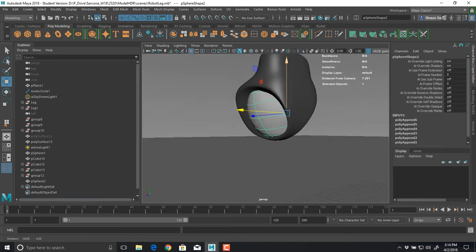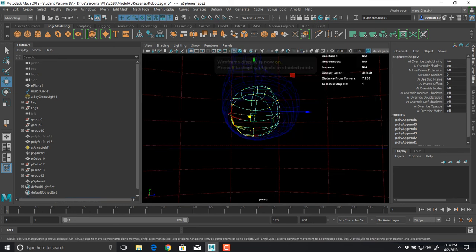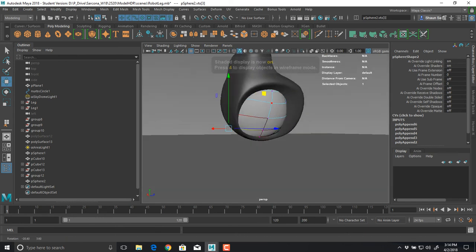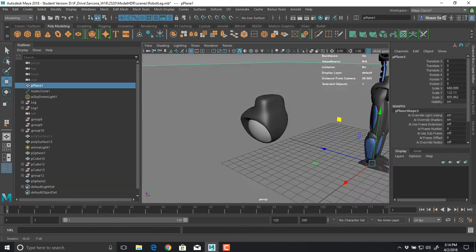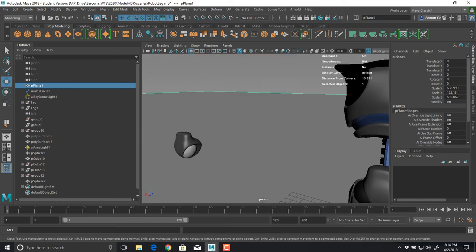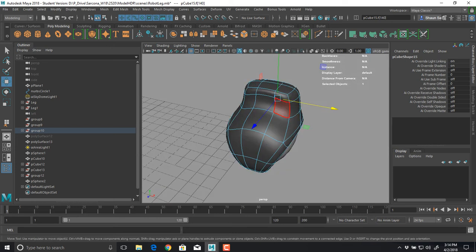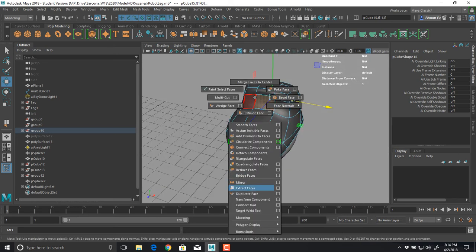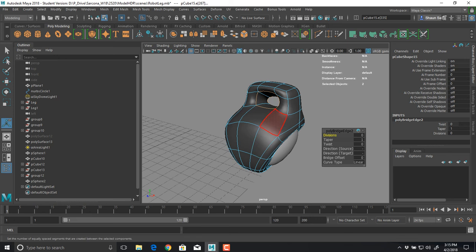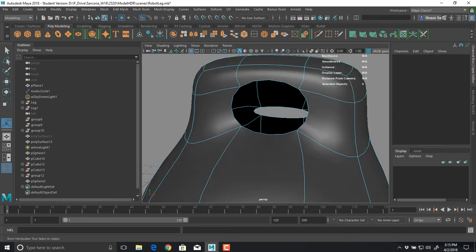And now I would have that shape kind of sitting inside there, and then I could give that a different color. And obviously tweak if I need to tweak. Let's see, it got moved a slight bit. There we go. Okay. And then the way that I created those holes was just the same way that I showed before. Click a face on the front, click a face on the back, and then just do a bridge, and it'll create a little cavity that you could then put whatever into. Okay, or you can delete it if you just want a hole there.